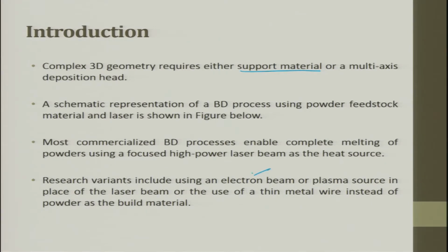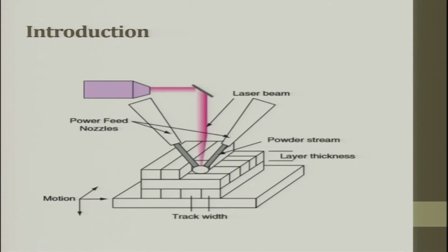See, the advantage of electron beam is that it is more focused, but the disadvantage is that it needs vacuum. Today we talk about low pressure or low vacuum systems for developing, and today electron beam is competing with laser beam in this beam delivery system in the rapid manufacturing way.